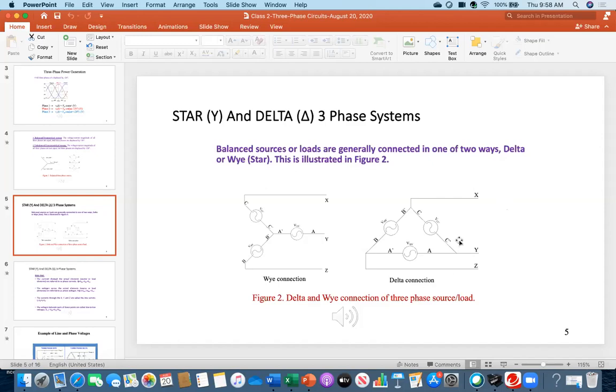That's why typically this arrangement is used in a portion of the power network where people don't need to use power. For example, 100-mile lines are going on, but people don't need to use power from there. So in that place, instead of the Y, use this system just to save the cost of the neutral cable.